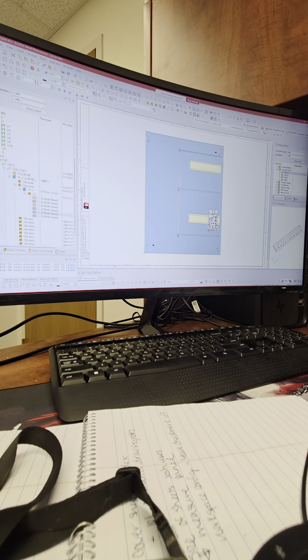Yeah, that's cool. All right, so let's just grab this GBK10 from a part number perspective. If you need this to be a different part number, then I would take this GBK10 in the library and just right click and say create new from this component. It's going to open up your library editor itself, but at least you have a component that is the ground bar.